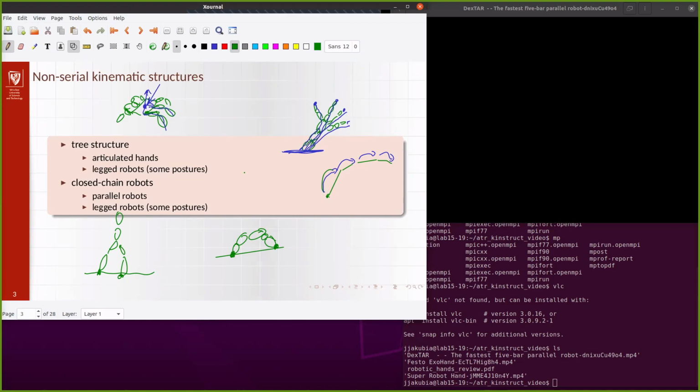We will see what the consequences are for the solutions that we have, especially in they will appear special. You will need to treat the closed chain robots especially because you can try to solve them using the standard kinematic approach, for example, like here, but the endpoint is not a free one. You cannot change it. So it is like a kinematic with a constraint that is fixed.